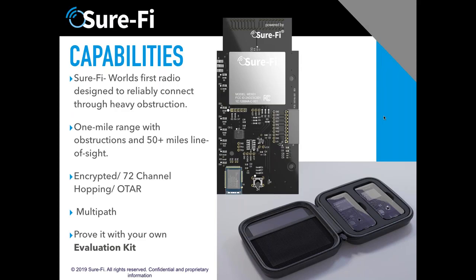Physical interfaces, he asked: RS-232, RS-485. And of course, there are adapters that can go to different things. I've tried it with an Ethernet cable, but you have to make sure it's not sending a local area network. That would be too much for the radio to send, but 232 and 485 are within reasonable ranges for the radio.